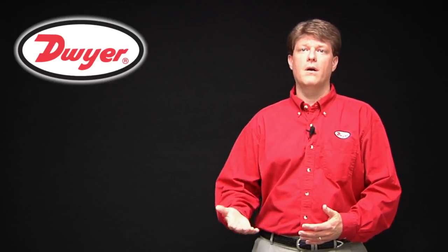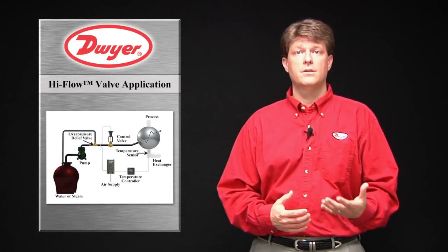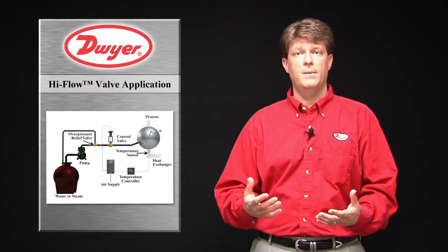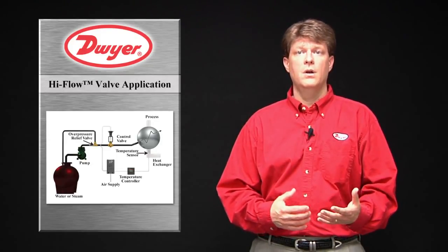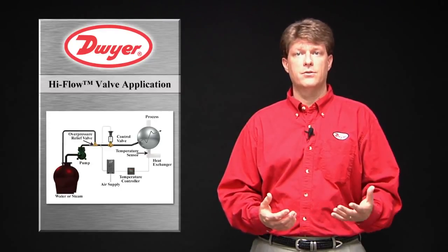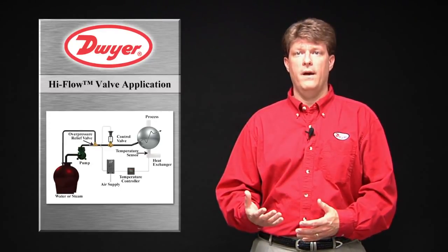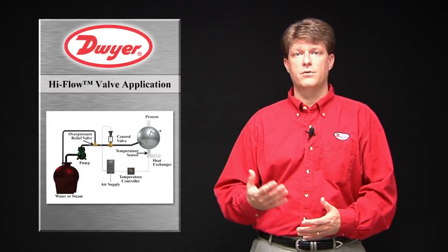In this video, I will cover control valve sizing. Control valves are used to change process conditions such as flow, temperature, level, and pH. A complete control system would include a sensor, controller, positioner, or current to pressure transducer, and the control valve. Globe valves, such as Dwyer's high flow series, are a very common type of control valve.